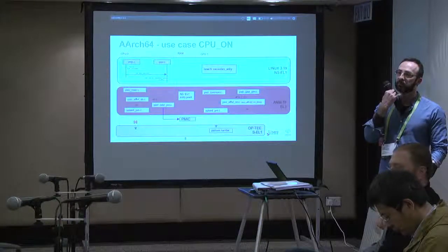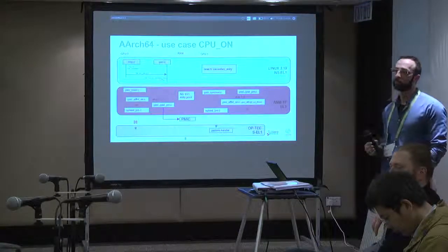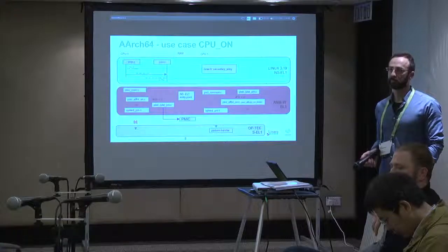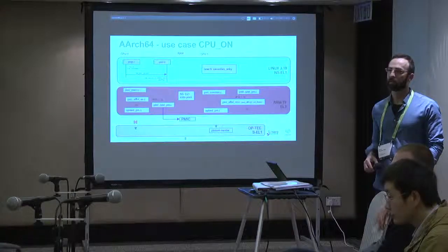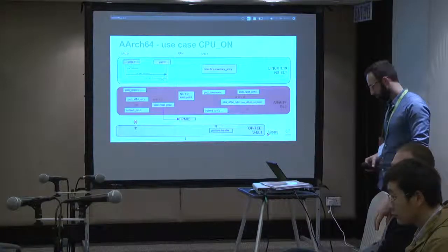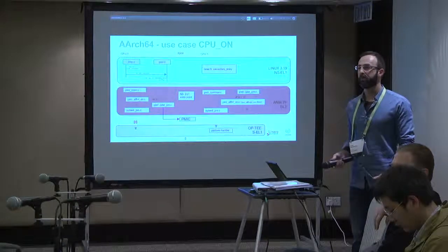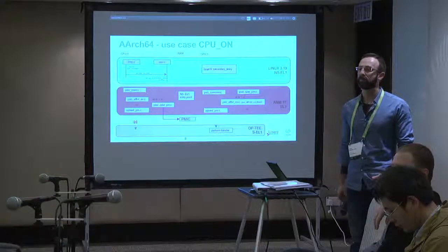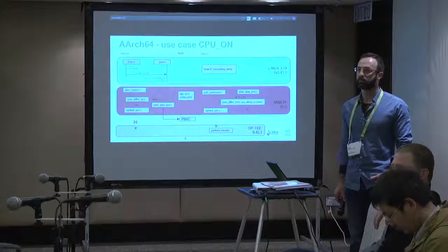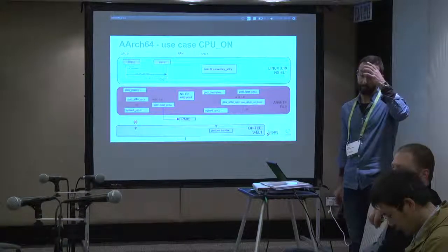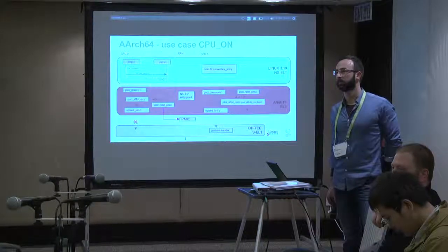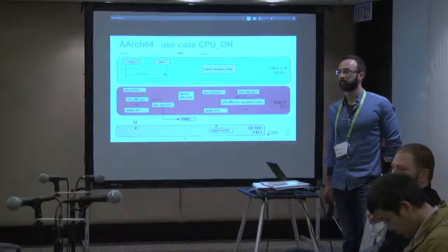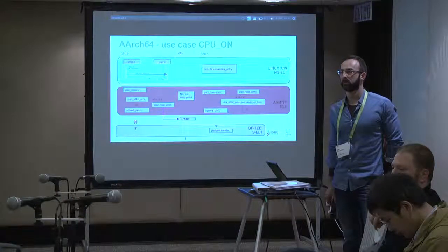Yeah, so Juno achieves this because that communication is done by the SCP. So of course that can manage its own I/O framework. In the process of actually doing the power down sequence, there are a number of steps, and at a certain point, returning to run OS code is absolutely impossible because of your state of coherency and cache state. And where in that sequence you would actually talk to the power controller to say, right, on the next WFI, when you actually get the signal that the core is in WFI, you're going to remove power.